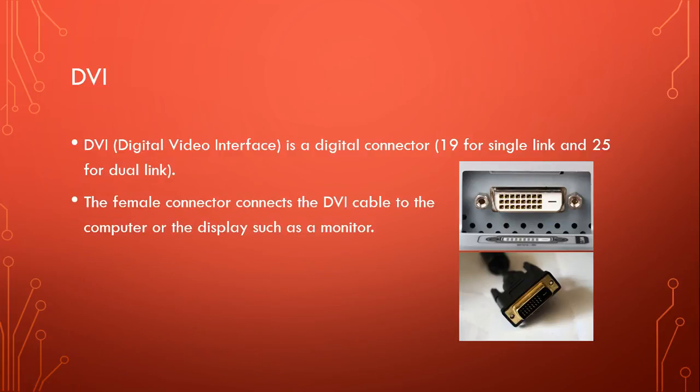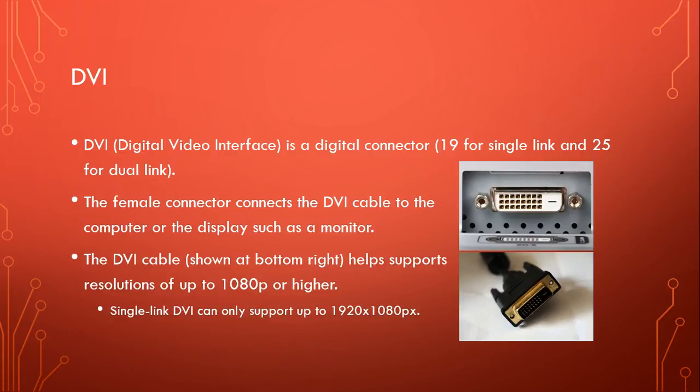Now the female connector connects the DVI cable to the computer or display, such as a monitor. The DVI cable, shown at the bottom right, helps support resolutions up to 1080p or higher. Now, an important thing to note, if it's not a dual link, if it's only single link, it can only support up to 1920 by 1080 pixels. So that's just your standard 1080p resolution.